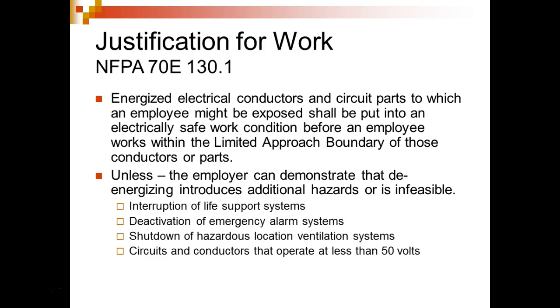Because if you have the wrong setting, if you have your meter set up wrong, what could you do? You could blow it up in your hands, yeah, and kill people, right? Or have big problems. So you got to be real careful, even on 50 volts, to verify your meter. In our classes, we're dealing with very low voltages in most of our classes, except when you get into motor controls, and you could cause big problems.